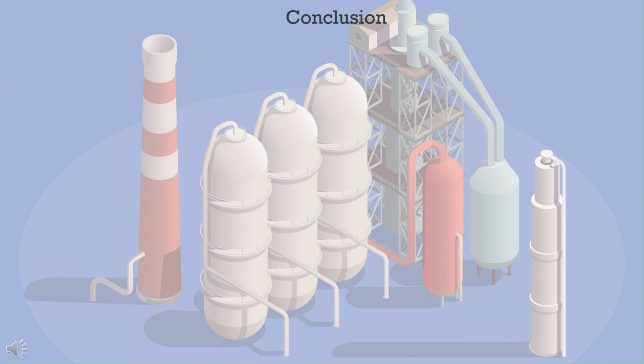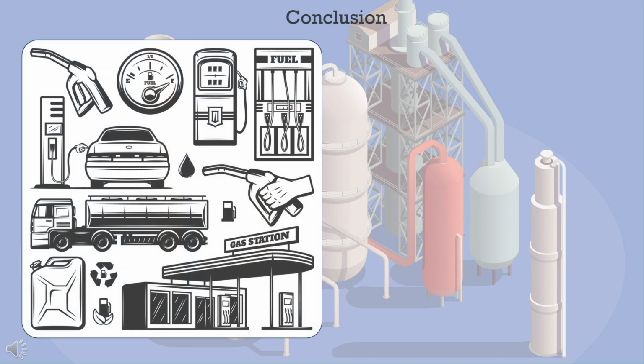Few key points are to be kept in consideration. Cleaning and inspection restores separation efficiency by removing fouling and detecting damage. Safety is ensured by proper blinding, gas testing, and confined space procedures.